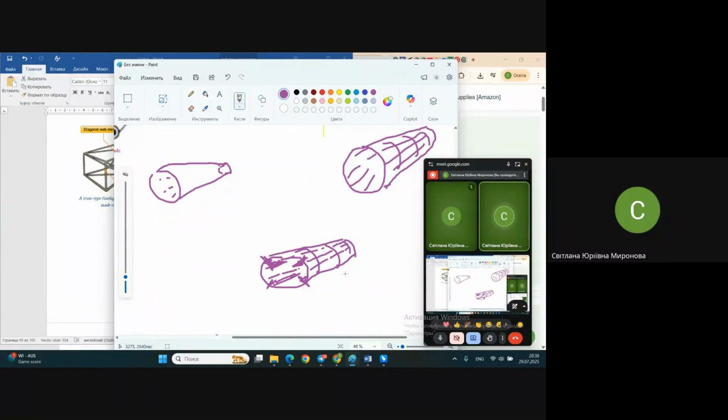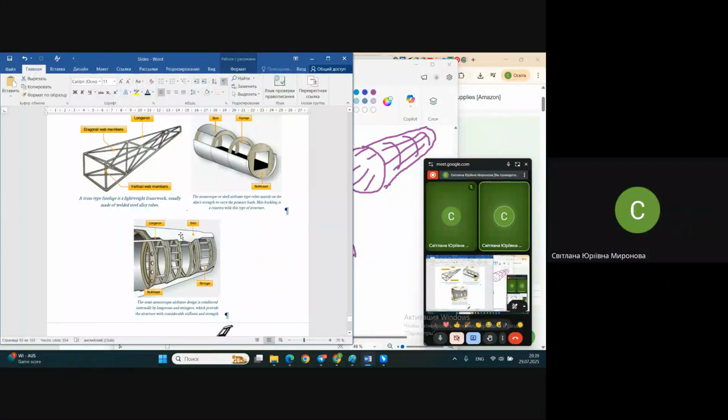And when it comes to some special places with high loads, for instance the place where you have the cargo door, you know, this openable piece in the aft fuselage, the ramp, so-called, at the end of the airplane, in this place it is better to use this longeron type structure. So I'd like you to understand that all three types you may actually meet in the same airplane, just in different places of the fuselage.